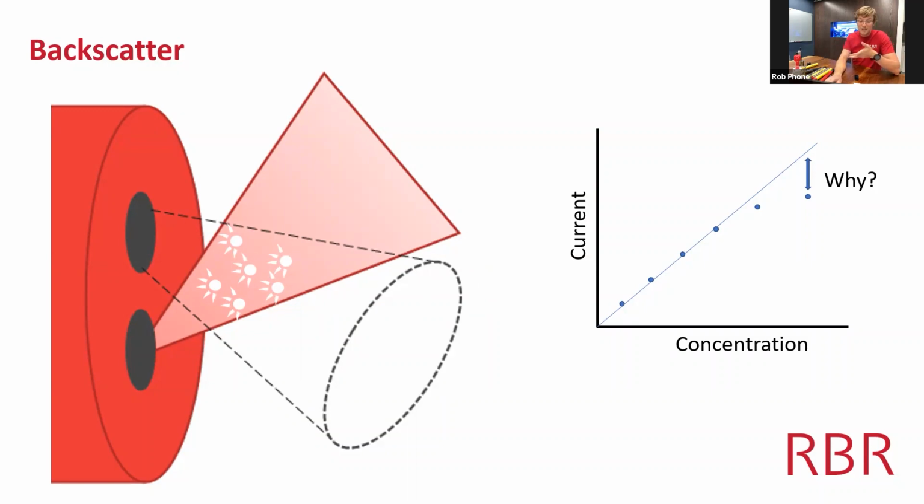The C-point has a unique method to get around this, where it adds a second photodiode at a different angle and at a much steeper angle. So this increases the linear range, but it does change the sample volume and reduces the resolution. But if you want to measure turbidity in the thousands of FTUs, this is the tool to do it.